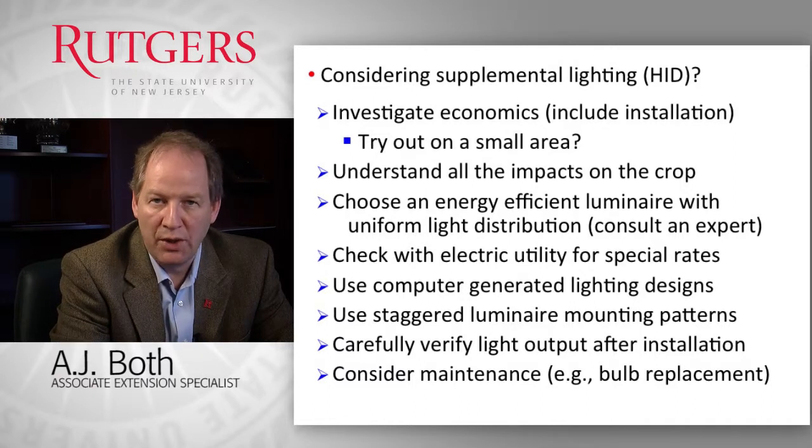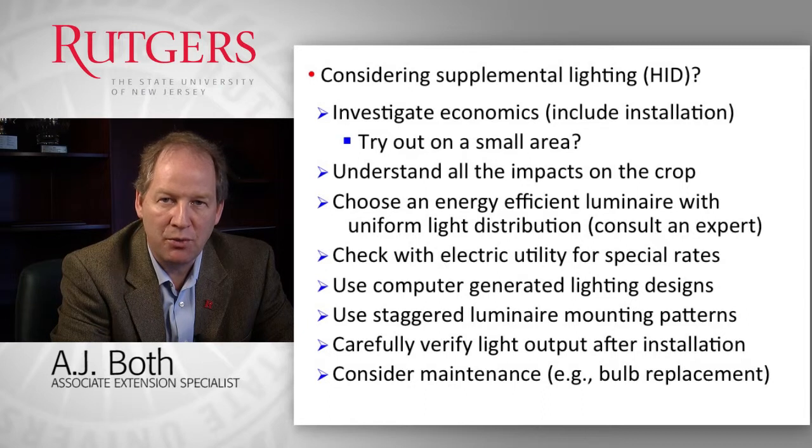I suggest you always use a staggered mounting pattern, so you stagger the lamps between rows for optimized uniformity. You will always want to carefully evaluate the installation after it's been installed, so measure the light intensity carefully after the system is installed and go back to the supplier and ask questions if you think you're not getting what you've ordered. And last, but don't forget, maintenance.